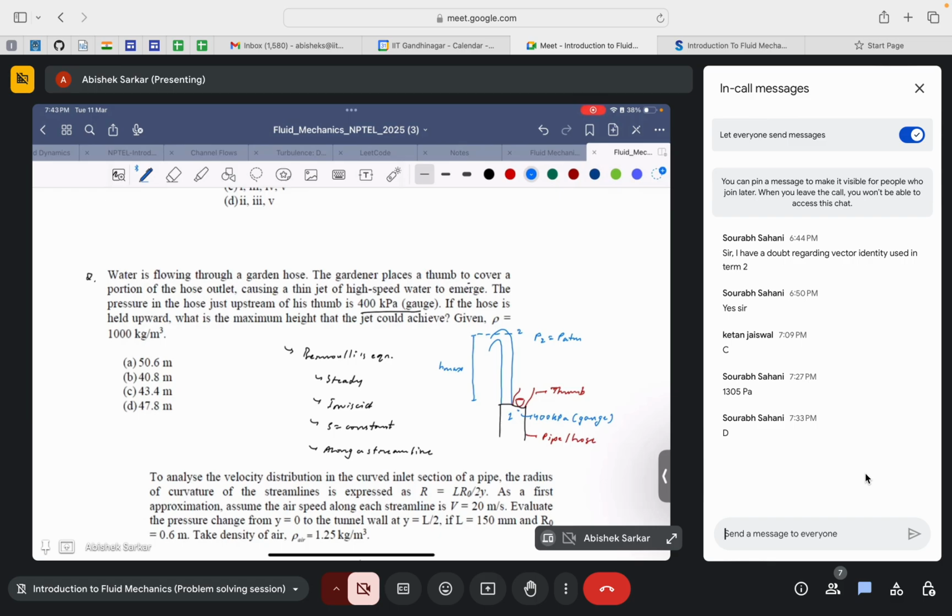See, let me give you something that I am learning as well, but it's good practice. While you're solving problems using Bernoulli's equation, a lot of times you will have to deal with approximations. Sometimes you may get an answer of say 2000 and your friend may get 1500, but the examiner may give both answers as correct, given that you have mentioned the assumptions you have taken while solving the question. Not any vague assumptions, but valid assumptions.